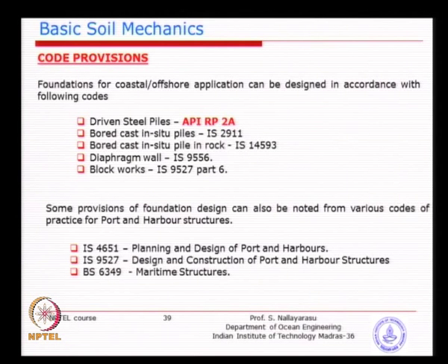But of course, you have other codes like bored cast in situ piles, IS 2911. There are 4 parts. I think it is available in our library also. And we also have bored piles in rock. This is bored pile in soil, either clay or sand, whereas bored piles in rock is a separate code, because of the nature of load transfer between pile and the soil.